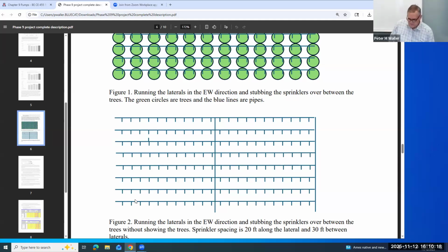So this sprinkler is going to be quite a bit different than this sprinkler if you have too much pressure loss in the submain. So you have to specify pipe sizes such that you don't have too much pressure loss in this submain. And I think I would definitely try to go downhill here, although the downhill is almost nothing, 0.02%. So I guess I wouldn't worry about it too much.